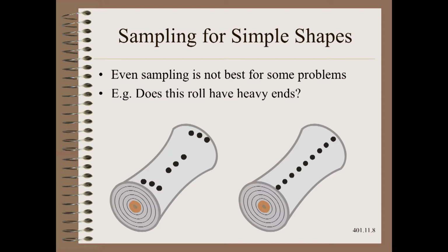However, a lot of the samples from the front quarter point to the middle and onto the back quarter point would be quite similar. On the other hand, you would only have a few on the edges where we are interested in studying. Instead, we could focus our efforts to put more measurements on the area of change near the edges, as with this sampling program. The distinction is that instead of finding out what the thickness profile is, we presume and check that it is smile-shaped, and then proceed accordingly to see if our instrument can see those high edges.